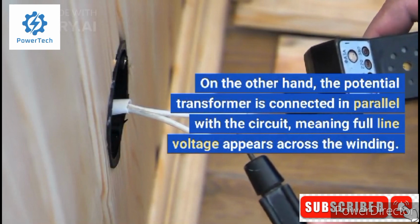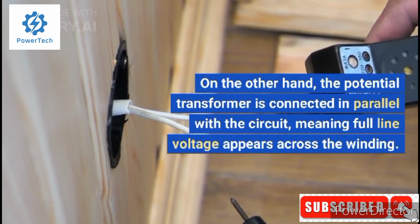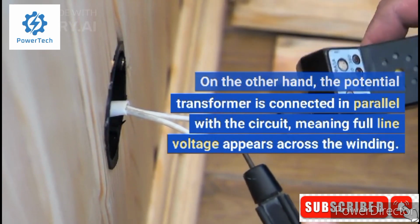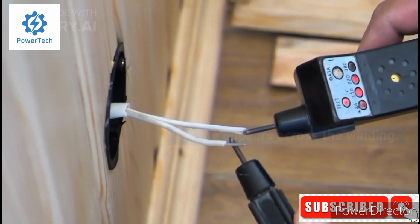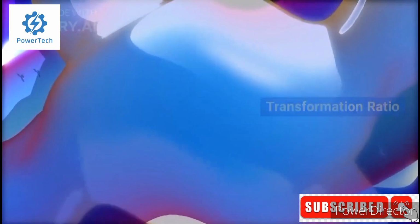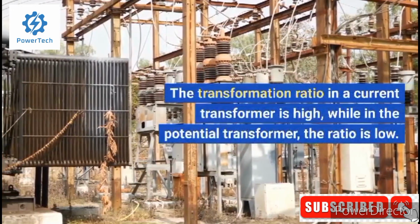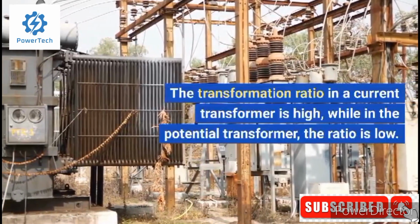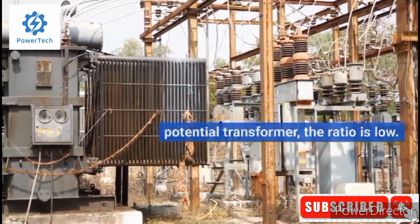On the other hand, the potential transformer is connected in parallel with the circuit, meaning full line voltage appears across the winding. Transformation ratio. The transformation ratio in a current transformer is high, while in the potential transformer, the ratio is low.